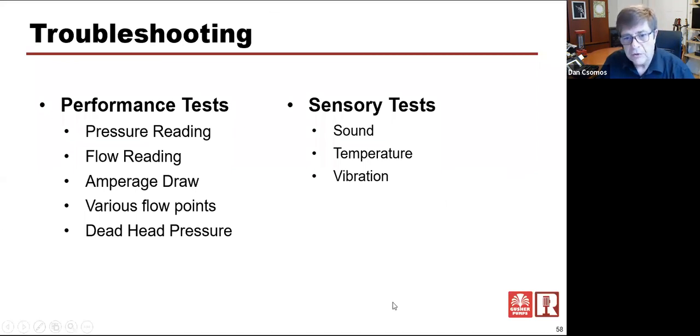So all of these things working together, vibration, you put your hand on the pump. Is it running smooth? Does it feel like it's healthy and happy, or does it feel like it's angry and upset? There's probably a reason for it. It may be an alignment issue. It might be cavitation. It might be air entrainment. There's a lot of things that can cause vibration as this thing runs.